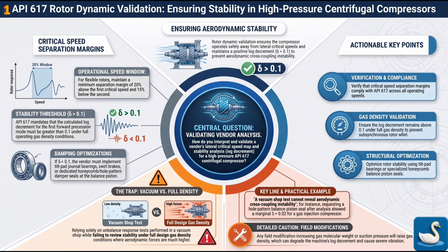In a compressor, that bump is a microscopic perturbation in gas density or pressure. If your log decrement is close to 0, your shock absorbers are effectively blown. You hit that microscopic bump, and the rotor just keeps bouncing. The vibration amplifies with every single revolution until the rotor deflects so far it actually hits the stationary casing. That paints a very clear picture.